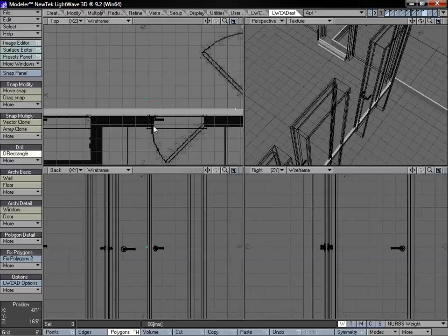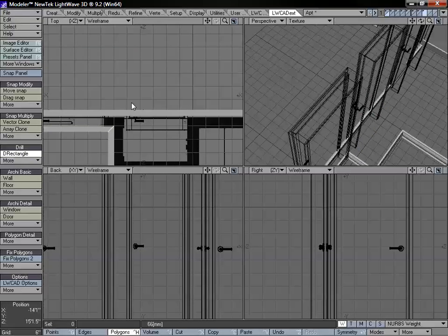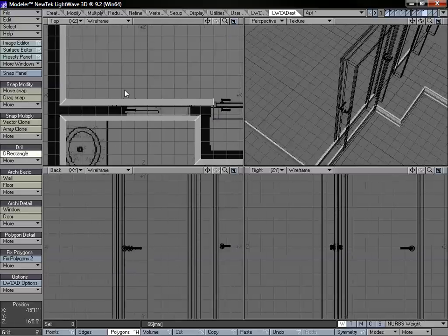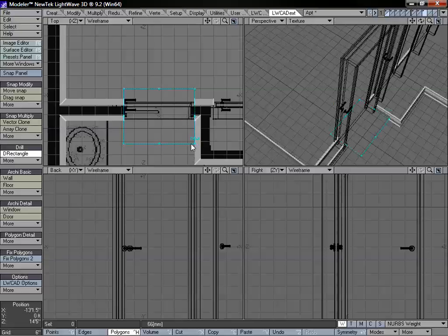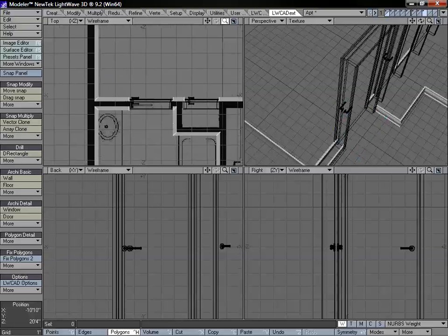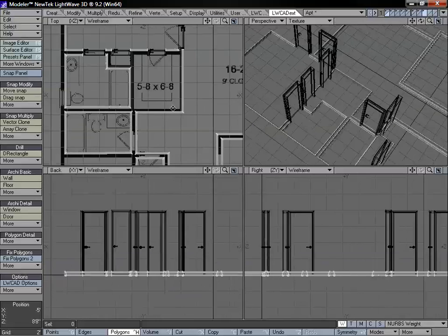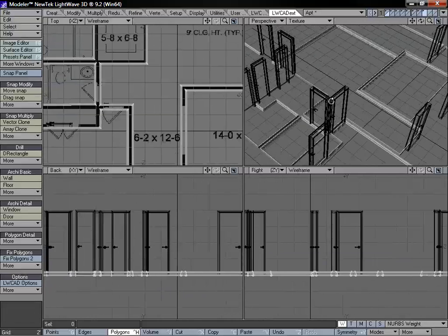And it's really quite easy since we have the ability to just snap to those door objects that are in the background. And we could just go throughout the entire model and quickly and easily remove all of the trim that isn't needed. And I might need to cut that one and be a little more specific about it. But overall, you basically get the idea.